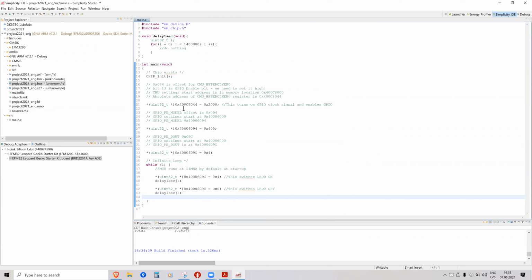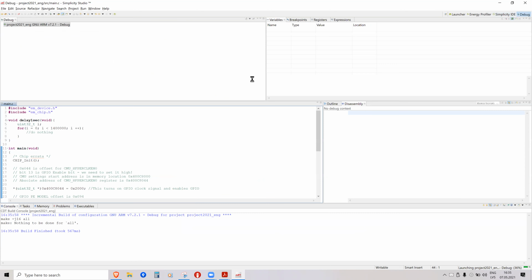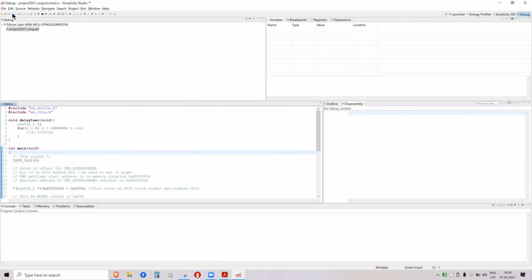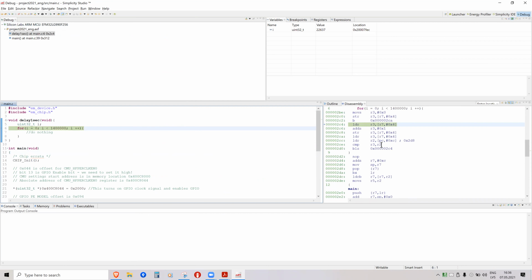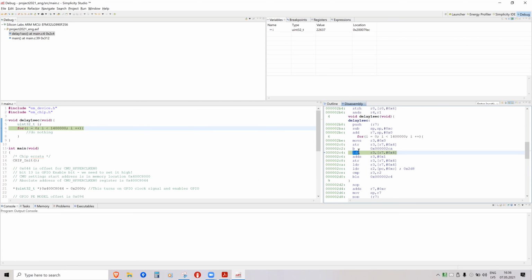Now, that is basically all for this lab work. So you can just write this code, do everything that I did, compile it, go into debugger, check out the disassembly window, and I'll give you some more information also. So let's say I'm in this debug mode. You can find information about the instructions by Googling their name and adding ARM in front of it.